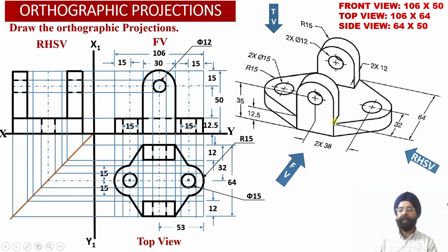because this has been obtained as an object line in the side view projections, and these object lines corresponding to the front walls are going to supersede the dotted line projections corresponding to the rear side walls of the vertical web. That is why a continuous object line projection will be visible in the right hand side view projections, which will be visible to the observer.